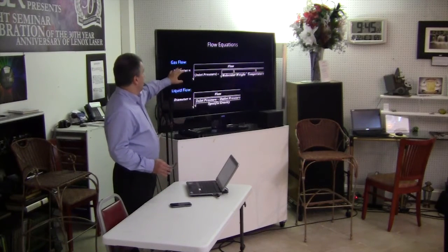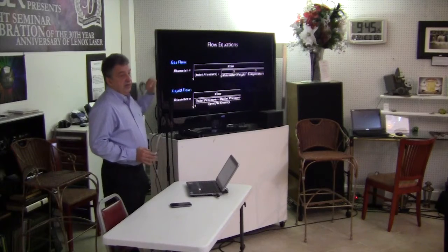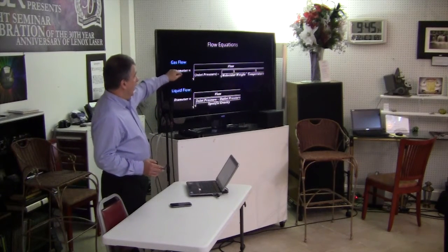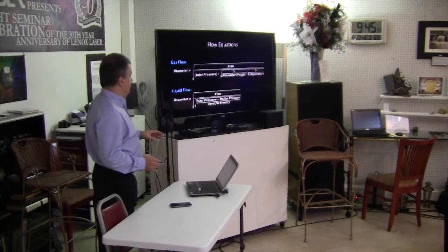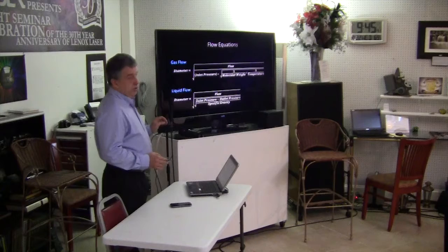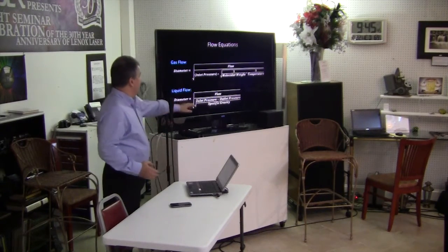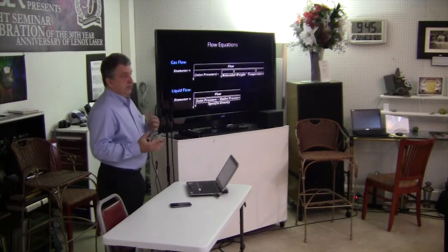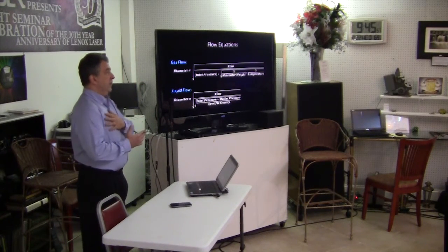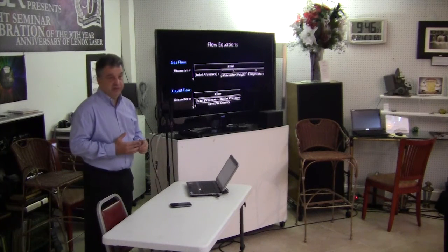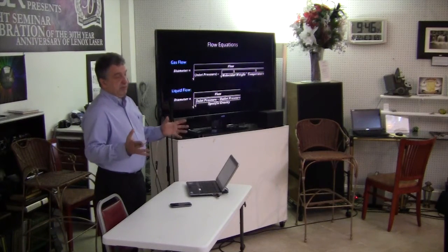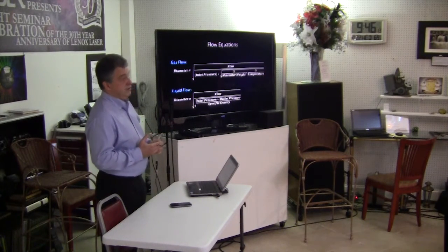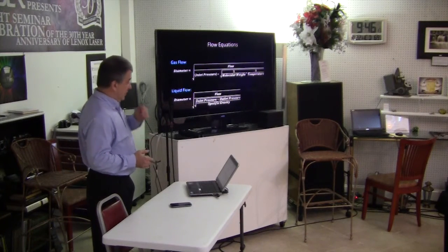So in other words, for the gases, the idea of this slide is just to show the sensitivity of the instrument. The system is very sensitive to the change of the pressure and not that sensitive to the change of the temperature and molecular weight. And if we flow the liquid, liquid is almost non-sensitive to the temperature at all. And specific gravity is a ratio of the weight of the liquid to the weight of the water. While you're doing that, you really have to understand the requirements for your environment, right? Because sometimes keeping the temperature of your environment is very important. Sometimes it's not. Keeping the pressure becomes more important, and so forth.